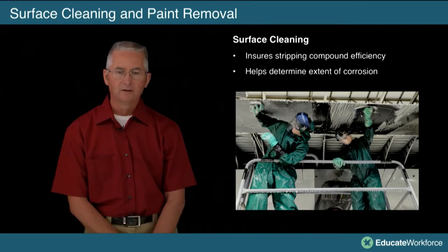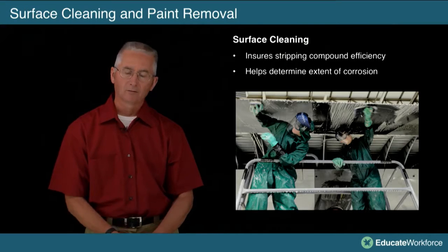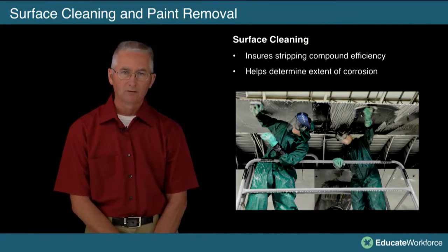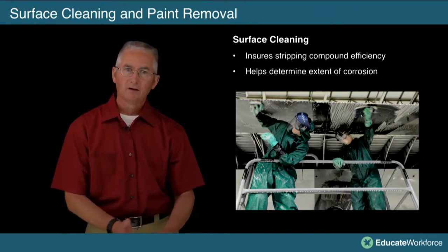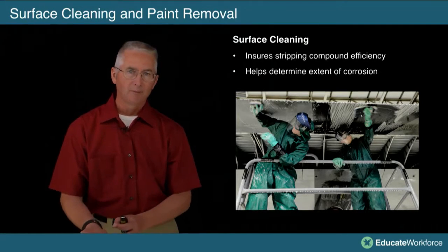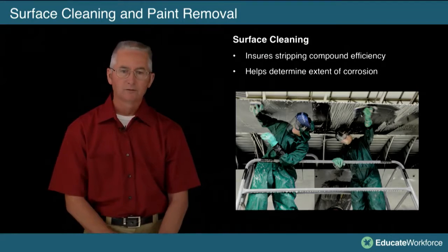So that's just stuff we need to determine, the extent of the corrosion, and see if we can figure out what's causing the corrosion. Again, remember we talked about batteries and battery acids. Is it exhaust fumes? Is it battery acid? What's causing the corrosion?